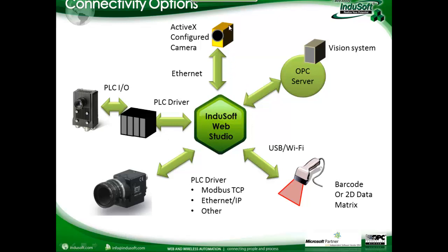There are certain types of cameras that have ActiveX configurations, so that within InduSoft Web Studio you could put their ActiveX configuration object on our screen, which would allow you to directly tie to the camera to configure it and then tell it to start or go and run its particular profile. Another way might be to have an OPC server built into the vision system. Then InduSoft Web Studio would be the client, and we could communicate directly to the OPC server built into the vision system. Another way might be as a keyboard input, or via Wi-Fi directly to some type of barcode scanner or 2D data matrix as well.